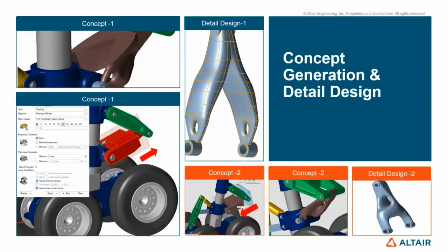If they can save each gram, there is a cumulative benefit. It's not only material saving, it is fuel cost saving, flying time saving, and so on. Similar is the case for satellites and many other things, right? That's where optimization, or mass optimization, plays a very important role. And predominantly, that's why topology optimization is one form of this optimization process.